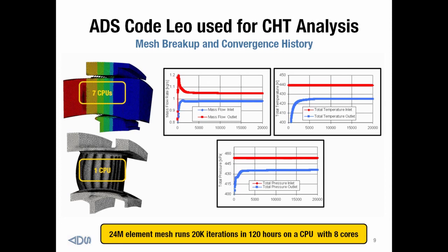And again, as we saw in the mass flow rate, the temperatures don't quite line up, and that's because of the injection of coolant flow. Finally, if we look at the total pressure, there's really three main sources accounting for the drop in total pressure here. There's the normal viscous loss, just from normal interaction between the airfoil surface and the fluid. But there's also, as the coolant flow is injected out of the airfoil, some loss due to the jet and cross flow viscous loss. And finally, you have a pretty significant amount of loss just due to pushing all that cooling flow out through these very tiny film holes.